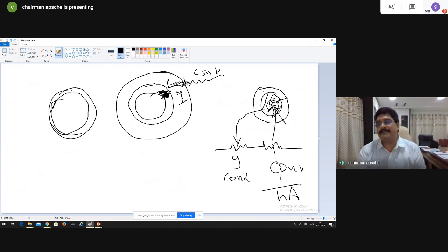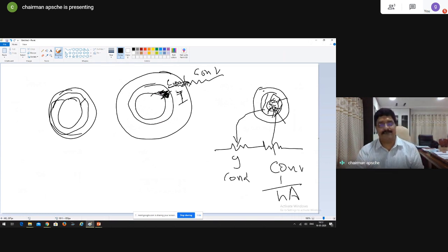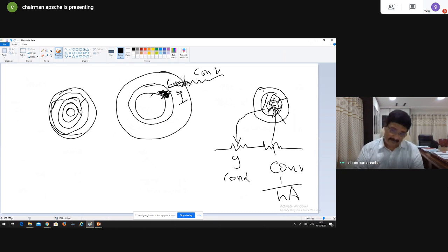Whereas here, what is happening? Both the resistances increase, because you are adding insulation inside, the conduction resistance increases. Resistance is added into it. Lagging happens there. And convection resistance, if you go on adding, the radius continuously decreases, and therefore the area decreases. Even convection resistance also increases. Both the resistances increase, and therefore you cannot have the concept of critical radius of insulation there. It is only going to lead to reduced heat transfer when you are insulating inside the pipe.